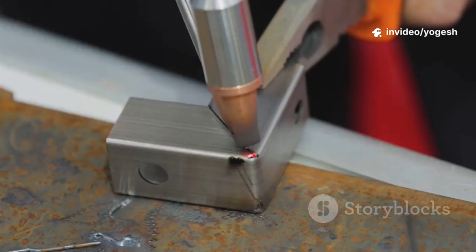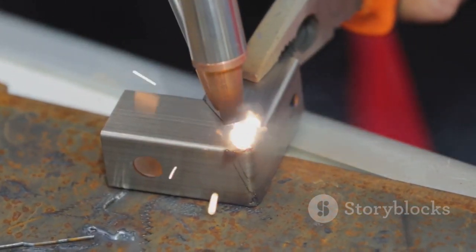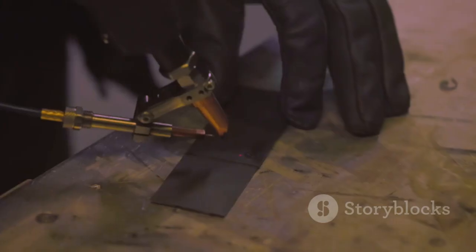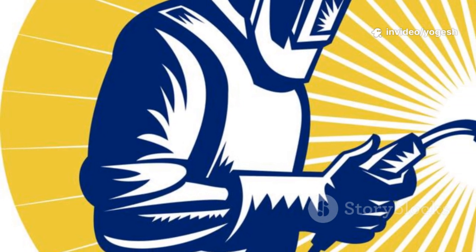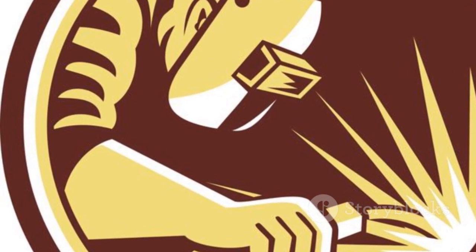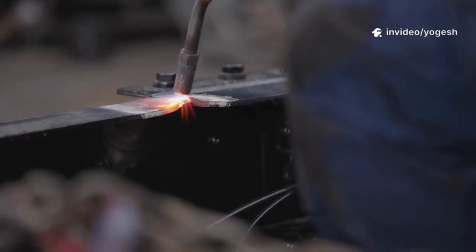A bent arrow indicates which member is to be prepared for a groove weld. At the opposite end, a tail is added only when extra information, like welding process or procedure, is needed. If no special notes are required, the tail is omitted. The reference line, arrow, and tail form the core structure of every welding symbol. All other details, weld type, size, length, build on this framework.